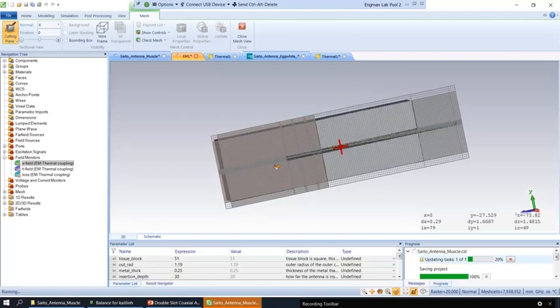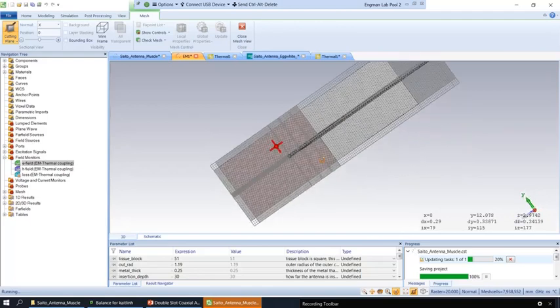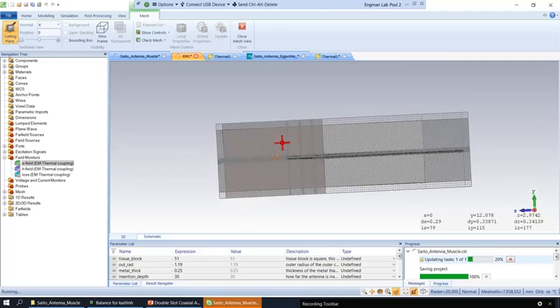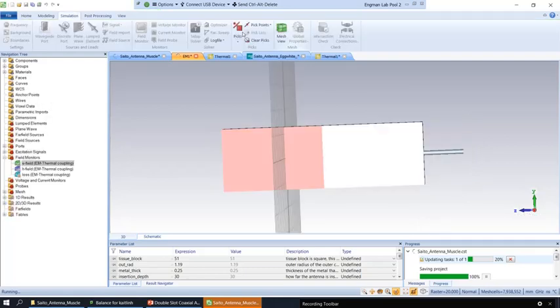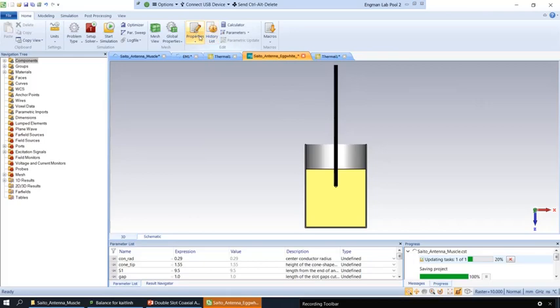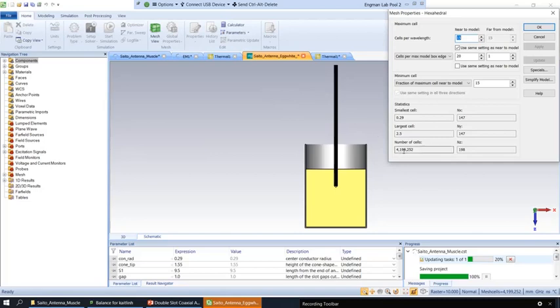See each of these little individual squares, we are using electromagnetics calculations on. If your mesh is too fine, your simulation will take forever to run and it will consume a lot of memory. In the case of running parameter sweeps where you're running a lot of simulations, it is in your best interest to decrease the mesh density and sacrifice some accuracy. So for example, this is currently at about 4.2 million cells. Now, when you already know what your simulation values are and you want a really clean, high resolution, accurate simulation, this is appropriate. But when you're doing a lot of testing, so maybe you're running 8 different possible parameters, this will take forever and it probably will crash.